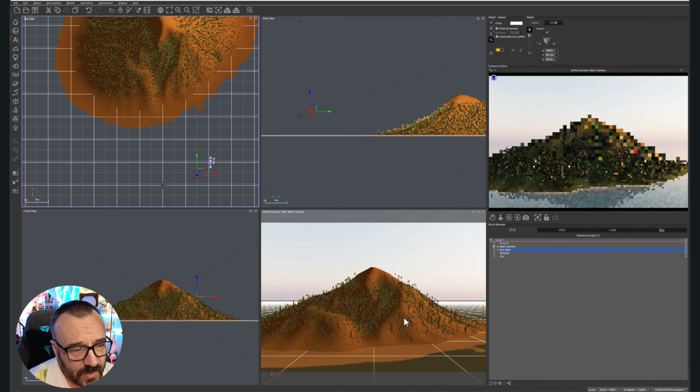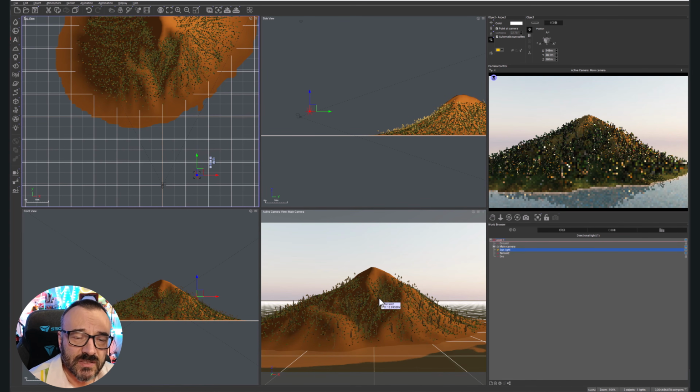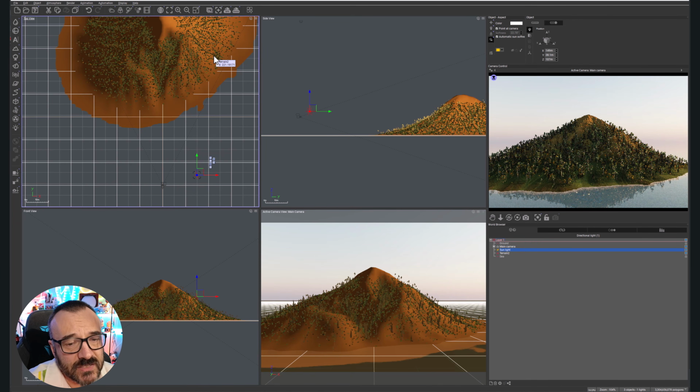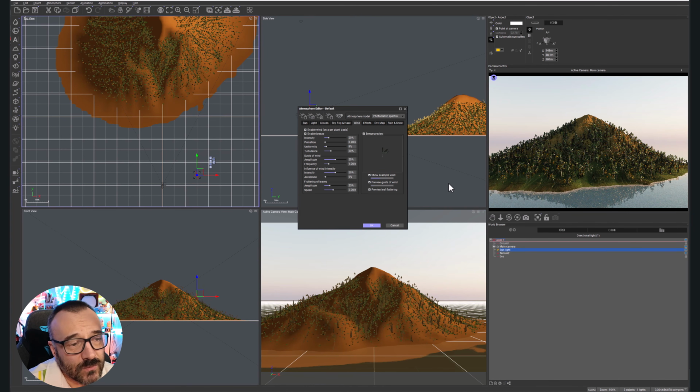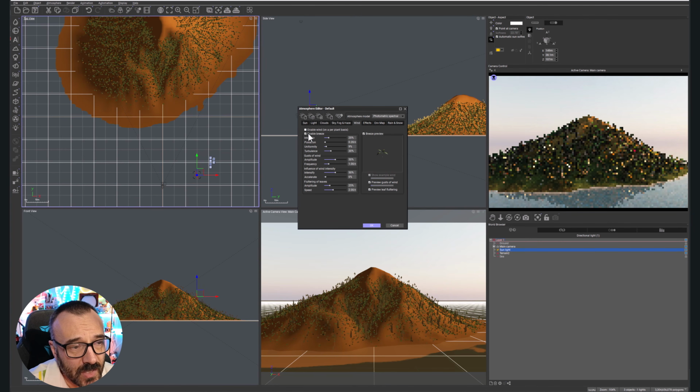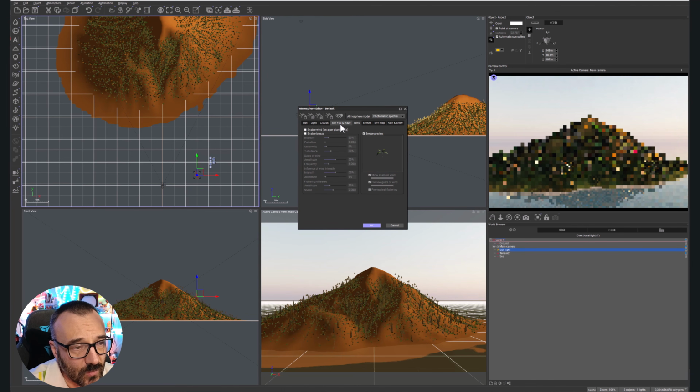And also notice when I rotate, I'm looking at the shadows in here, because shadows are what give us depth, and you can see we're creating an area. Also, right now we're utilizing the model photometrics, and photometrics is very nice and accurate, but when I create illustrations, I actually like to switch to something different. For this we'll go to the atmosphere editor. We looked at it a little before. Let's disable animations because we're not going to use them.